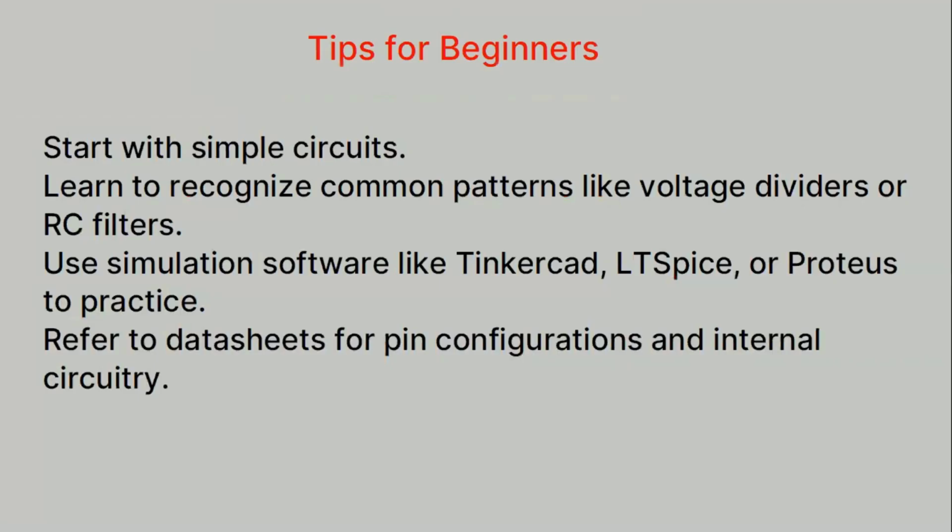Next slide. Tips for beginners who are just starting: what you have to see in the circuit when you see a circuit. Learn to recognize common patterns like voltage dividers or RC filters. Resistor to resistor connected together is called a voltage divider, which we have seen previously, or maybe I will tell you in the coming session.